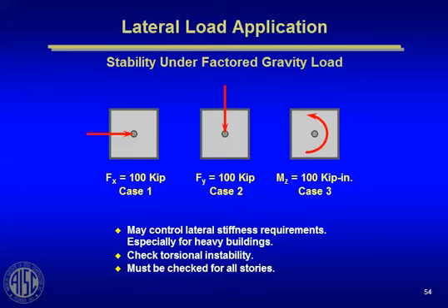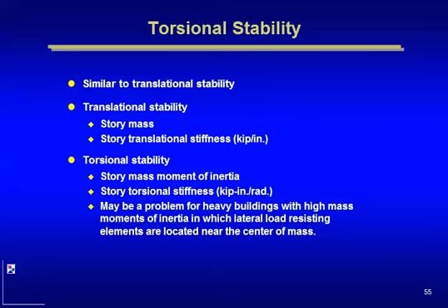Let's talk about torsional stability, because some engineers aren't used to this concept and don't understand why it's important. We all know what translational stiffness is, right? You apply a load and you have a certain stiffness in the frame that produces a certain deflection under that applied load.